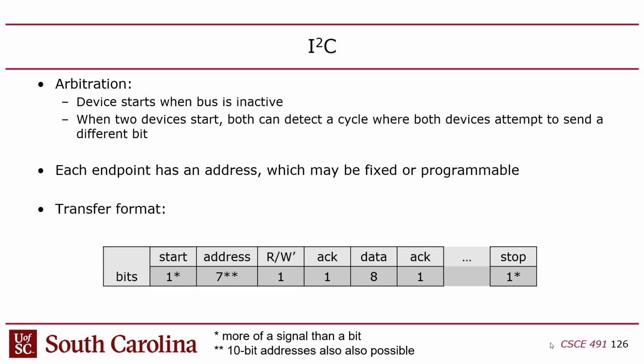So I'll take my hands off of it. So after I send 8 bits, the address is 7, the read-write flag is 1, I send 8 bits out, hands off, and the control of the data line is switched from the master to the slave, so the slave can acknowledge just the address part, the header, right? Does that make sense?